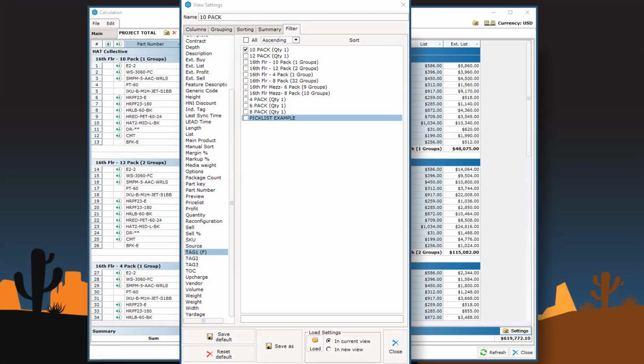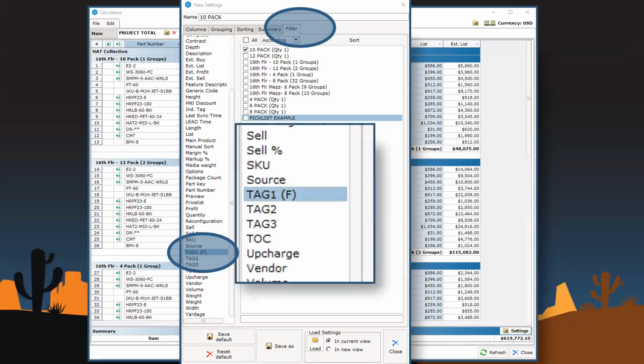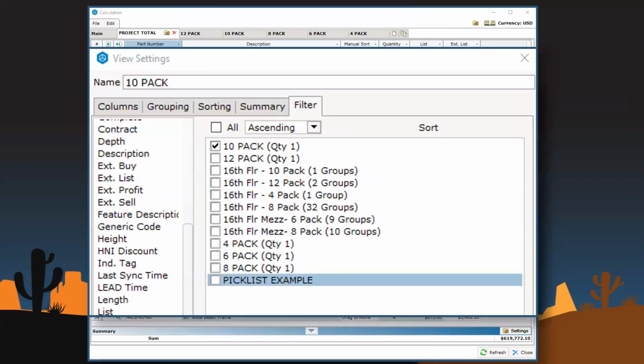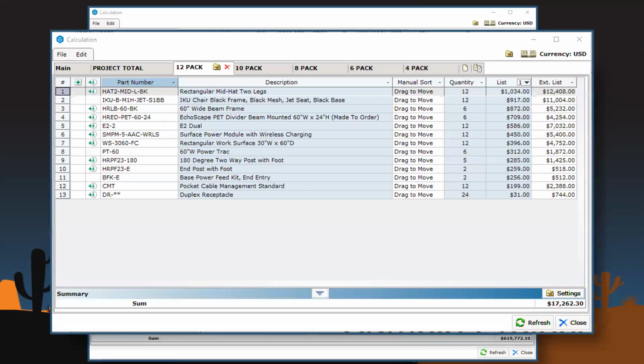Filtering is for focusing in on the information you want to relay or have visible. This is what I utilize the most for the paper spaces and article views. It's easy to spot if a filter has been applied. You will see the F right there. And that's telling us that someone who's been in the drawing has applied a filter. So it's easy to track down if something's going on. Here's a look at my tag screen and all the tags I have off, making focus tabs like this possible.